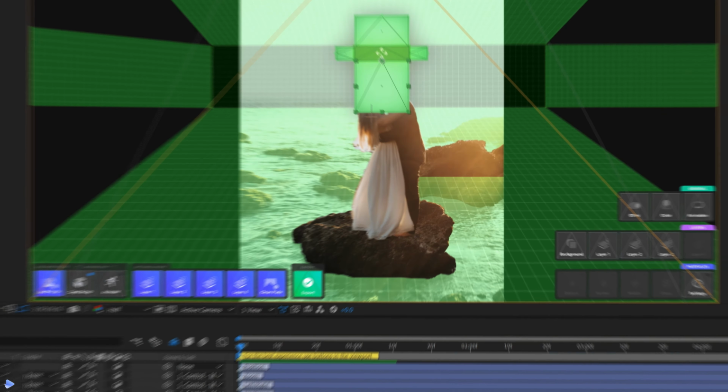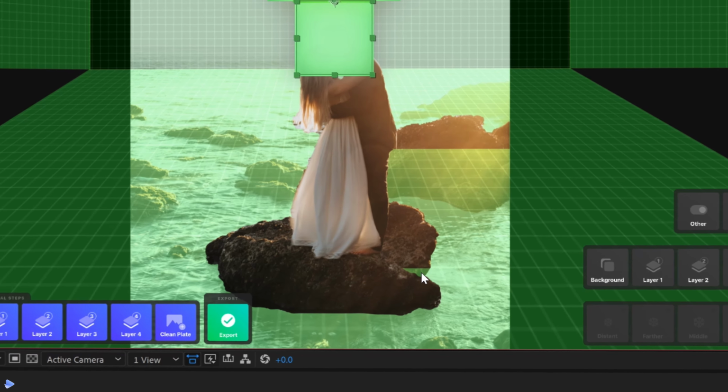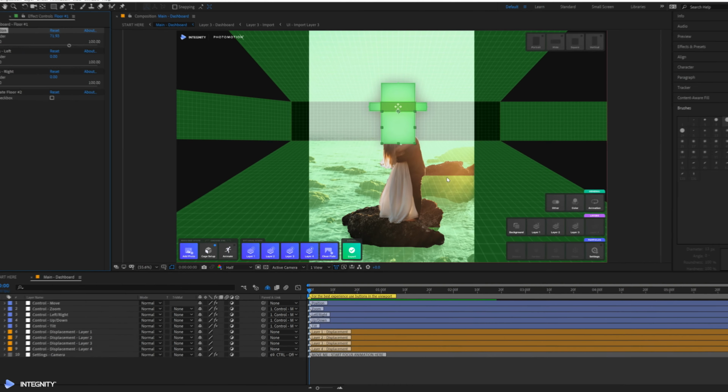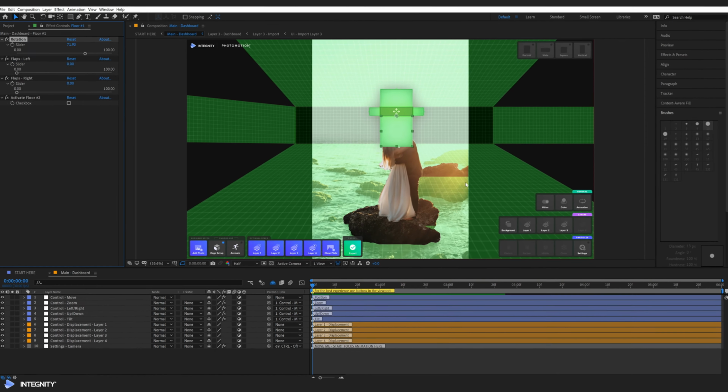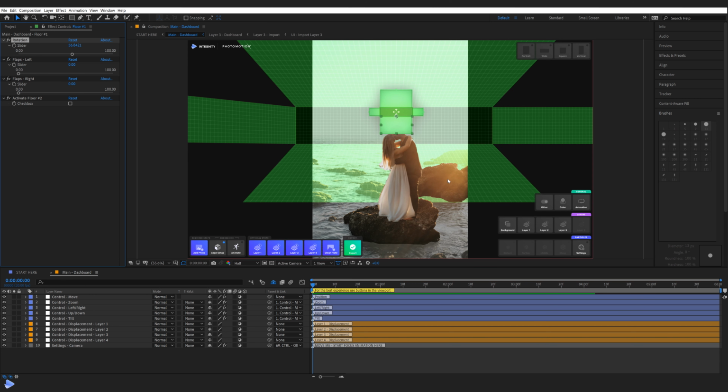If you keep doing that, you can see that we are now running into issues with layer number 3. Layer number 2 again seems like it is intersecting, but this is intersecting way too much. So what we have to do is go back to where it was, 56, because now we can be sure that that is the actual slope of that floor plate for layer number 3. And all you have to do is create another floor plate that is coming from floor plate 1.